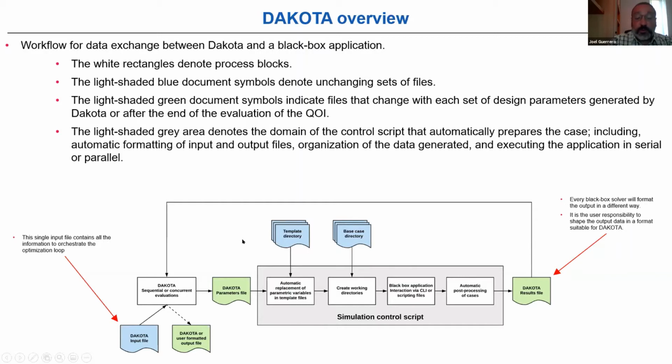In OpenFOAM, you should be able to identify what your parametric variables are. See that you have some template directories. In this template directory is where you are going to insert these parameters, and then you keep running. This is a context control here, and here you have this simulator script that can usually use bash scripting, but it can be anything that you want to use.